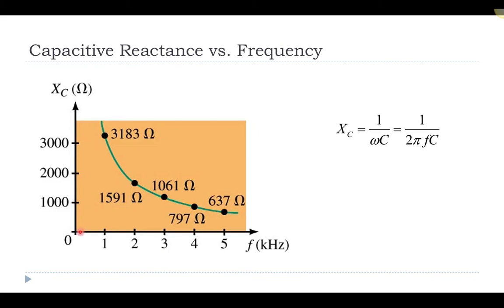Versus as the frequency goes towards 0 over here, that means the capacitive reactance gets really big. So if the frequency goes to 0, that means your capacitor is just charging and charging, and eventually it's almost like DC, right? So the capacitor will just charge up, and then it'll act like an open circuit again. So this relationship actually makes a lot of sense in terms of what we know about DC and just transient current and voltage when you have inductors and capacitors.